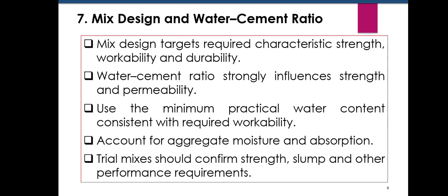So next is about mix design and water cement ratio. Mix design aims to achieve the required characteristics: strength, workability and durability. Water cement ratio is one of the most important parameters because it strongly influences the strength and permeability. So we should use minimum water content necessary to obtain the required workability. We also need to account for aggregate moisture and absorption. Before production, trial mixes can be used to confirm strength, slump and other performance requirements.